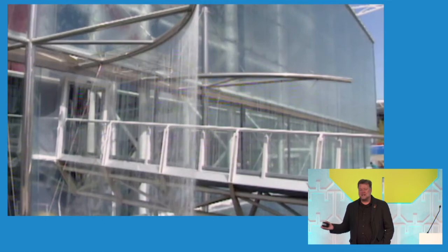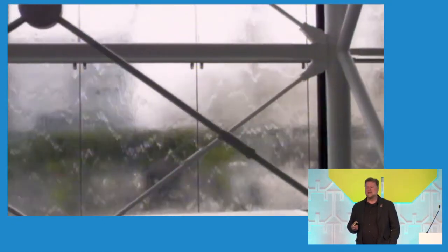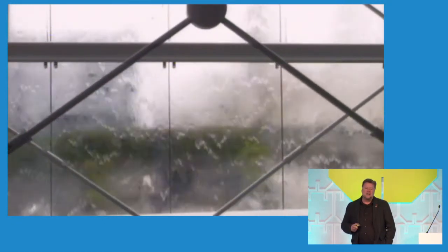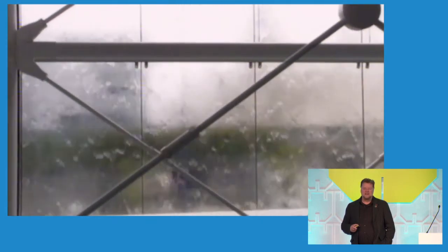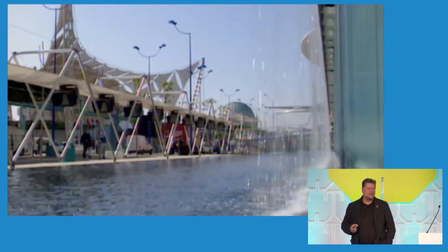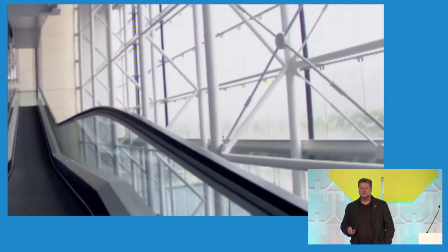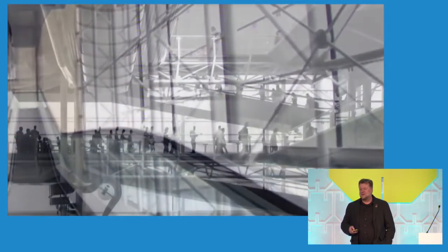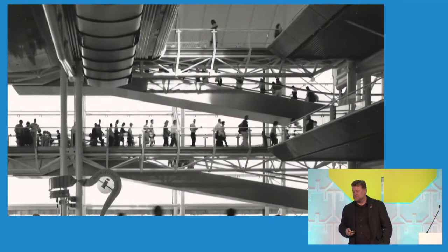But the beauty was that as the sun hit the wall, unlike a brise-soleil, which means you're in shade, it took all the infrared out of the sunlight. So when you went inside the building, it was very bright and light, and yet it was completely cool. And so, the sun was actually cooling the building.